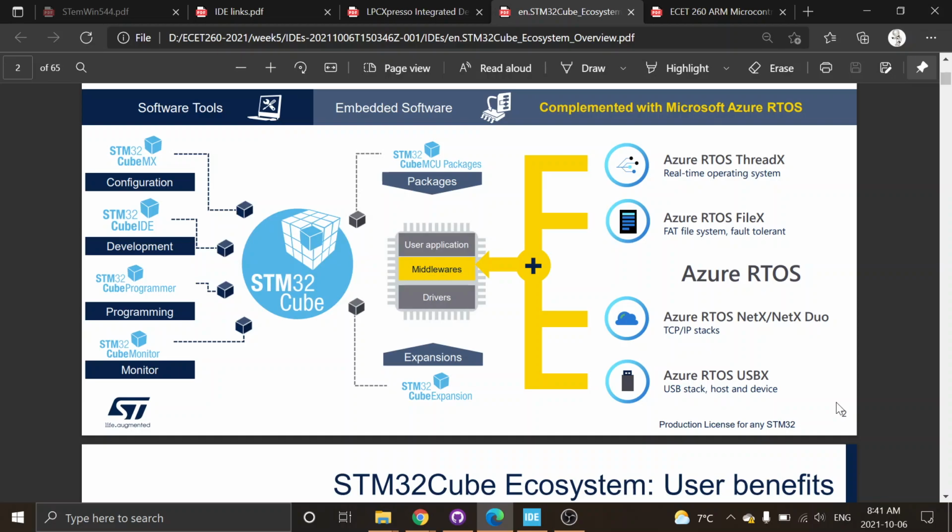Since ST-Link V2 was out, they emulate a flash USB stick, so you can just drag and drop a binary file on there and it will program it. You can find the binary file in your debug environment and just drop it over and it will program. And it actually gives you a little text file that says whether everything's good or whether there was an error.